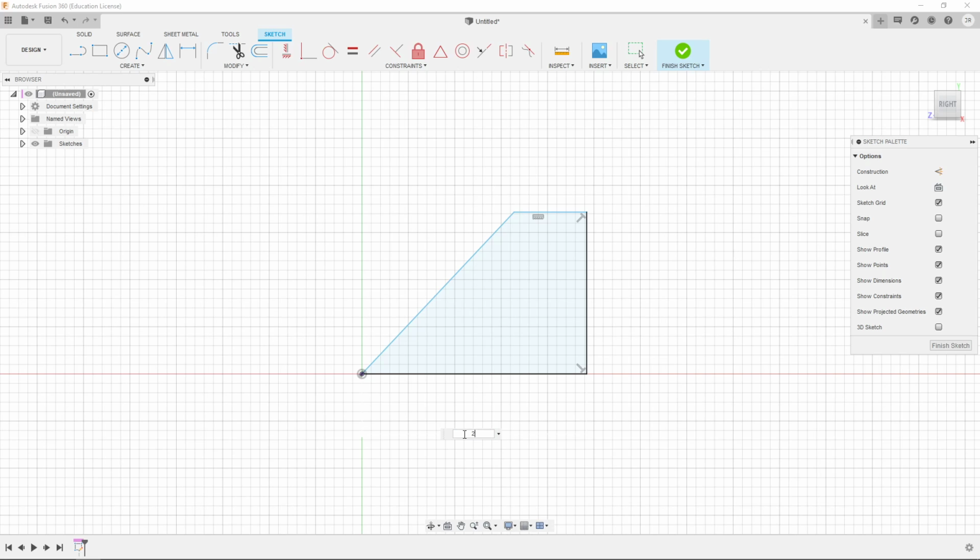So I'm going to type 26, and that is millimeters by default. If I hit enter, notice it got a little bit longer because I was pretty close. I had done 24 point something, and so now I'm at 26 millimeters. And notice this thing here is just a reference as a dimension, so I can always double click on it to change the number if I want. Or I can leave it alone, and I can always move it around if it's in the way. So if I want to see this better, 26 from here to here.